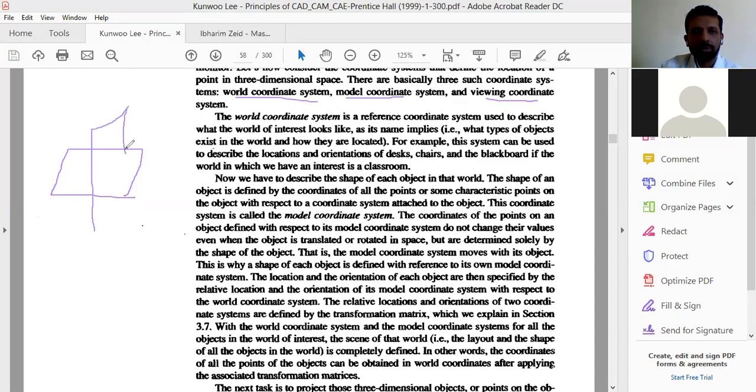So we'll be able to see something like this in the CAD softwares, right? So this will be for the side view, this will be for the horizontal plane, and here we'll have one more for the front view. So we'll have these three planes coming up into the picture. We'll select any one of the planes and then start sketching.